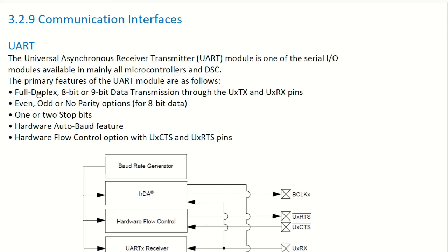So we have the most common one, the UART or the SCI, serial control interface. The universal asynchronous receiver transmission, UART, is the most common name for microcontrollers, and this is a very old one. At logical levels of 5 volts or 3.3 volts, we call it UART, and at industrial levels it is called RS232. It's the same one, there's just the levels that are inverted and amplified.